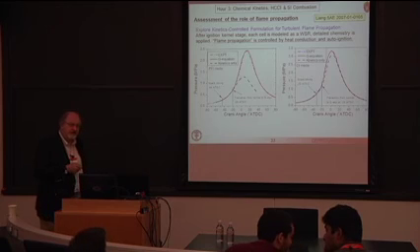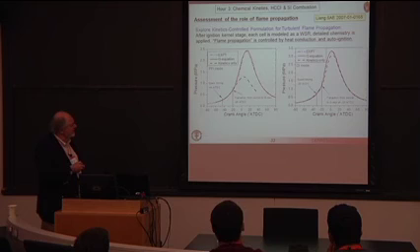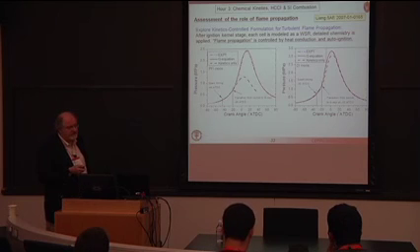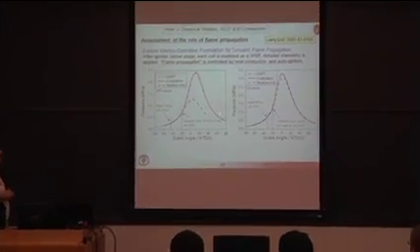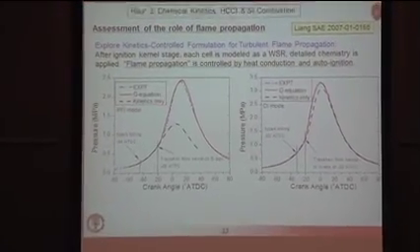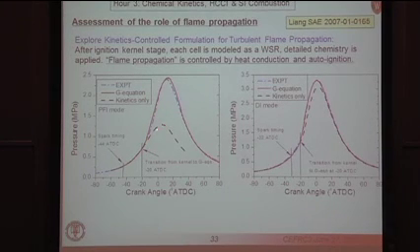The final thing I want to talk about: we spoke about how flame propagation is important in a spark ignition engine. What if we turn off that G model and simply use chemical kinetics to determine the combustion process? That's shown here, cylinder pressure versus crank angle. Here you see the experimental data in blue. The G model I just showed you is in red. But if we turn off flame propagation, we find that we're just not able to calculate the proper fuel to products conversion rate.